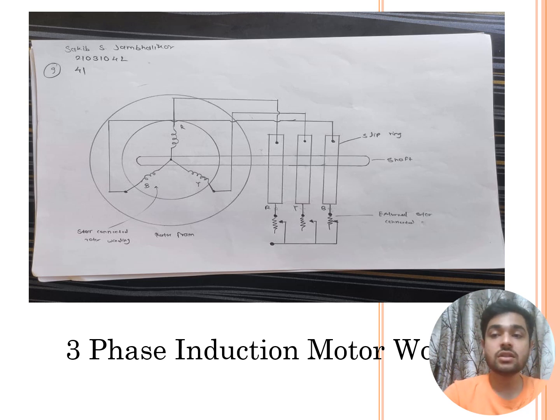Hence, as per Lenz's law, the rotor opposes the cause, that is, the relative velocity. Thus, from the working principle of the three-phase induction motor, it may be observed that the rotor speed should not reach the synchronous speed. As I mentioned, the synchronous speed formula is determined by the stator. If the speeds become equal, there will be no relative speed, so no EMF is induced in the rotor, no current will flow, and therefore no torque will be generated. Consequently, the rotor cannot reach the synchronous speed.